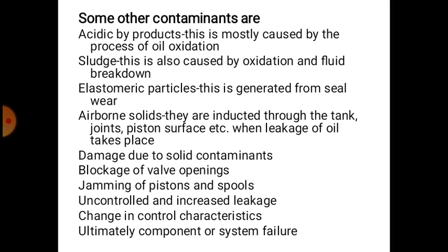Some other contaminants are acidic byproducts. This is mostly caused by the process of oil oxidation. Sludge: this is also caused by oxidation and fluid breakdown. Elastomeric particles: these are generated from seal wear. Airborne solids: they are inducted through the tank, joints, piston surface, etc., when leakage of oil takes place.